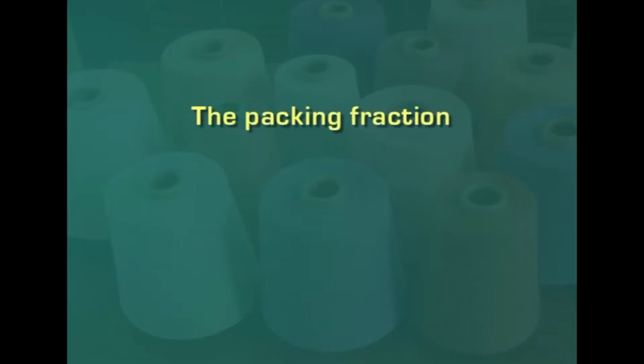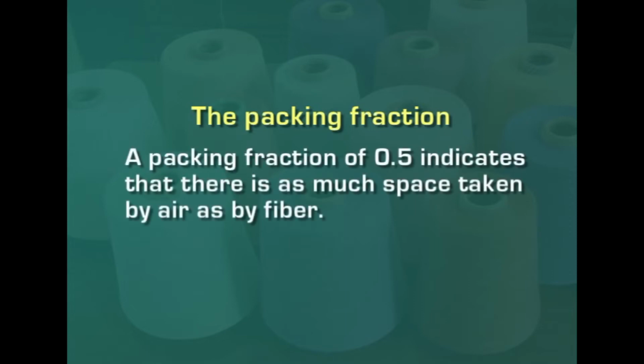Apart from that, we also see that there is air that is also incorporated during the structuring or the manufacturing process of the yarn. So, this we call a packing fraction, which indicates the amount of space that is enclosed by the fibers. If we say, for example, it is a 0.5 packing fraction, that means the amount of air present would be equal to the amount of fiber that is present in it. The major factors would influence here based on the structure of the yarn, because the packing fraction,